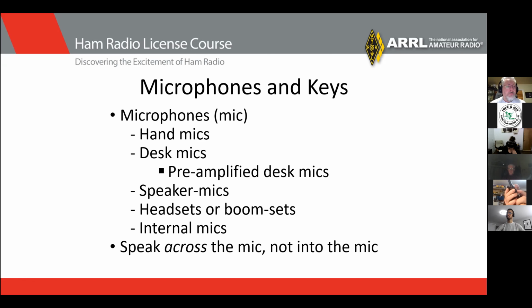And then you got your push to talk button right here, and you got a talk around button here that lets you listen to the input. If someone is not getting the repeater, sometimes you can hear them when a repeater can't, and let you reverse around it. This is going to be your on off, and you change frequency by just pushing the numbers in on the keypad here. And when you hit 6 numbers or 4 numbers, it'll go to that frequency.